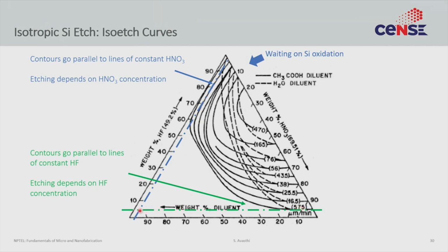If you change the concentration of HF from 5% to say 10%, this line shifts up, and now irrespective of how much HNO3 you put in, you get an etching rate of 16.5. Once again, the complementary situation. Your etching rate seems to be decided by the component that is least present in the system, in this case that is hydrofluoric acid. What is happening?